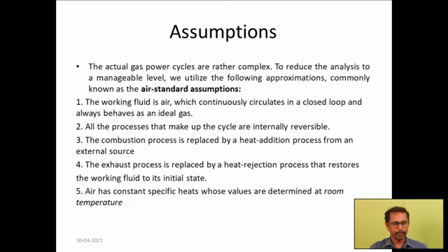The actual gas power cycles are rather complex, as we already discussed. To reduce the analysis to a manageable level, we utilize the following approximations, commonly known as the air-standard assumptions. The working fluid is air, which continuously circulates in a closed loop and always behaves as an ideal gas. So we have to consider that the working fluid is air and it should behave as an ideal gas, so that we can compare all the cycles.